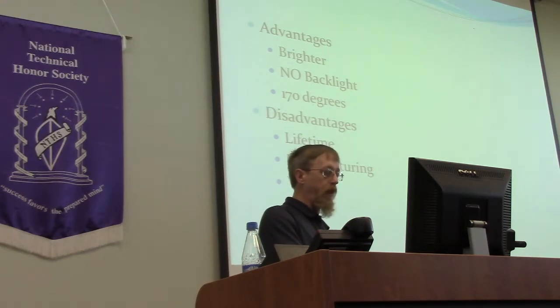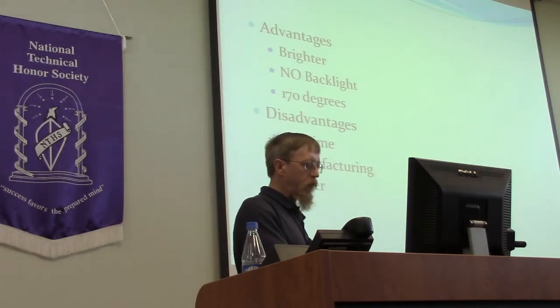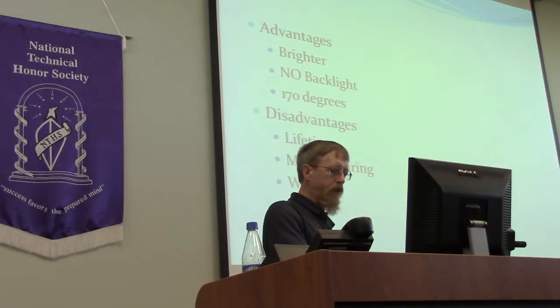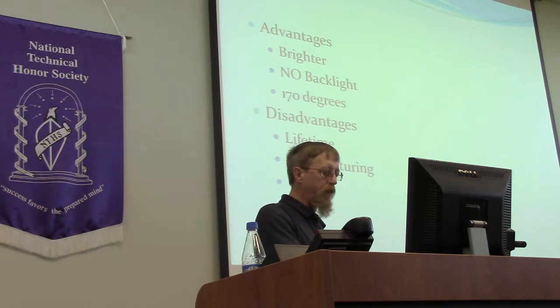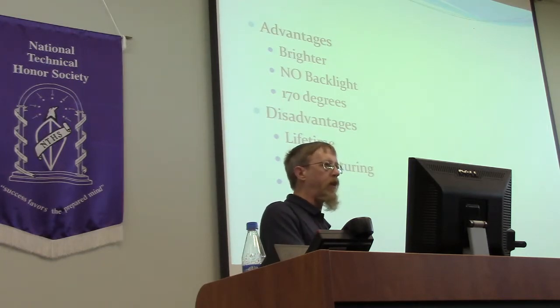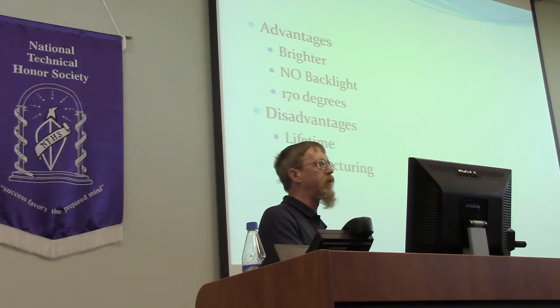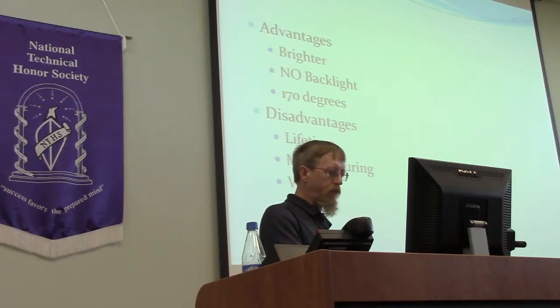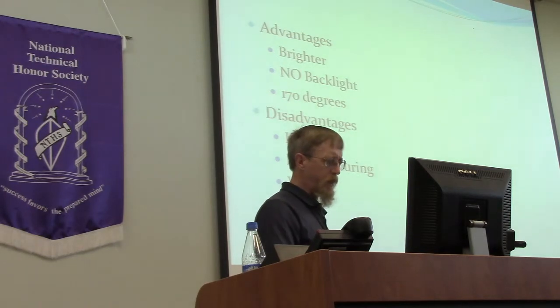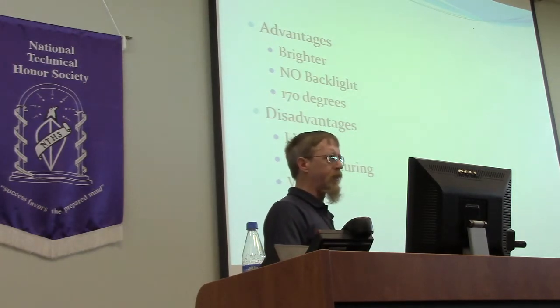Now, the problem with the OLEDs is the lifetime. The red and green have a sustained life, but the blue they're having trouble with because it decomposes so quickly. At the max right now, they're only saying that it'll hold up to about 1,400 hours. So it's not very long on that. In normal consumption, I think it works out to something like about 8 years or so. So it's not something that's going to die on you as soon as you buy it.